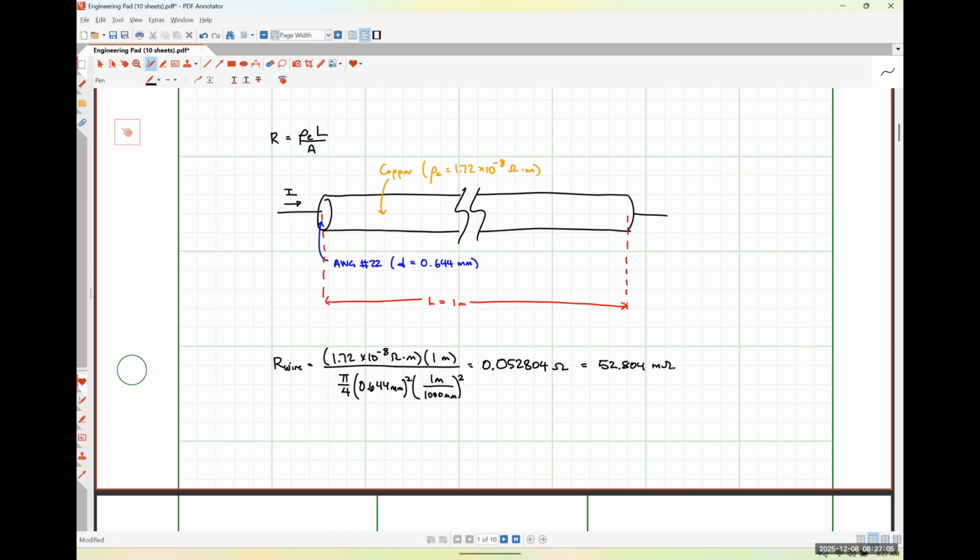What's the smallest resistor that you guys used in your 120 series? It's the one that made the LED most bright. 220. So a 220 ohm resistor is the smallest one that you guys use. The largest ones were probably 10 kilo ohm or 20 kilo ohm resistors when you were setting up your single-ended ratiometric measure, your voltage divider network. Sorry for getting fancy there.